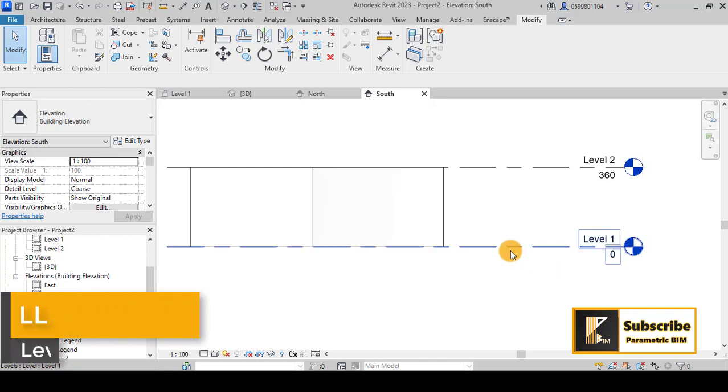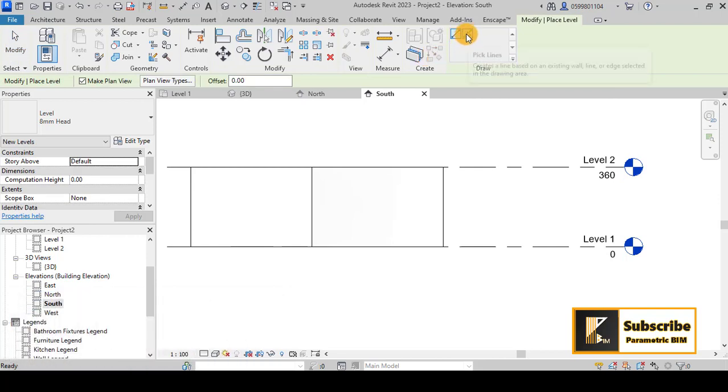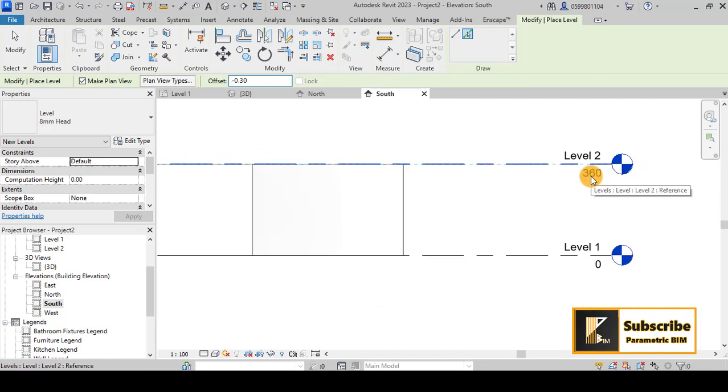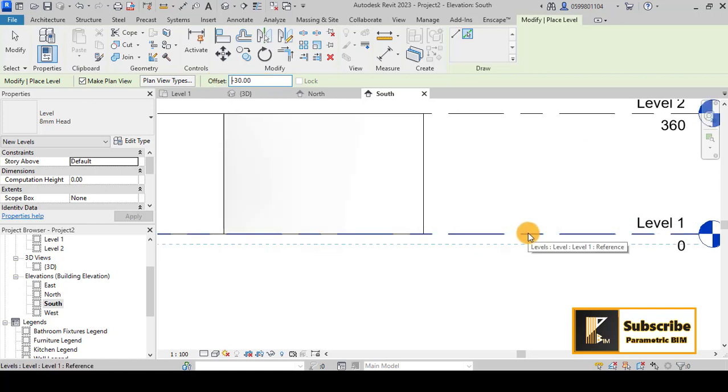So I will click on the level and create similar, and then I will pick this level, but let's give here for the offset minus 0.3 because I am working in meter. No, it's in centimeter here in Revit, so I have to put minus 30 here, and let's put it below the 0.